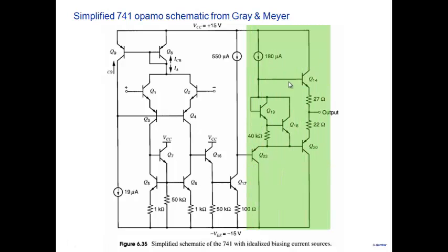Do we now feel comfortable with this part? Right? We've just shown you a class AB stage here. These are the two diodes. This is the PNP stage. This is a current which biases the diode here. So you should not feel too scared of a stage like this now. Okay, so this is a standard class AB stage. This one that you see here is, as I just explained, a common emitter stage with the active load here. They've just put a current source.